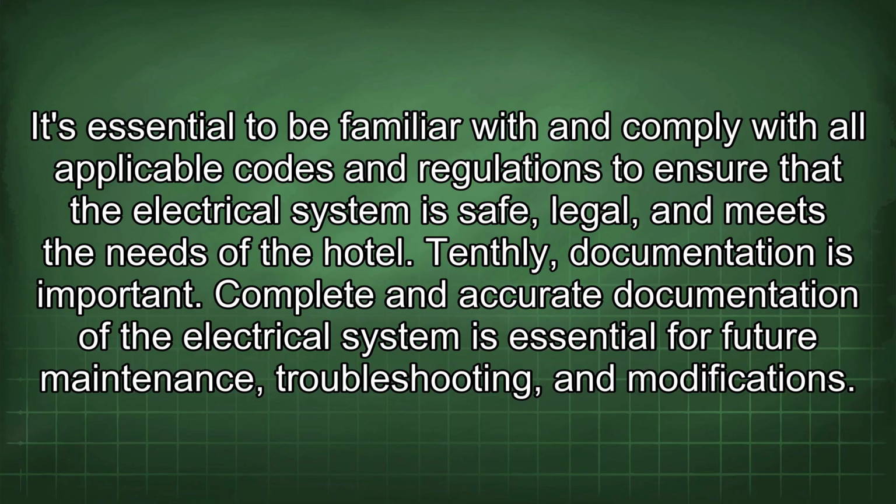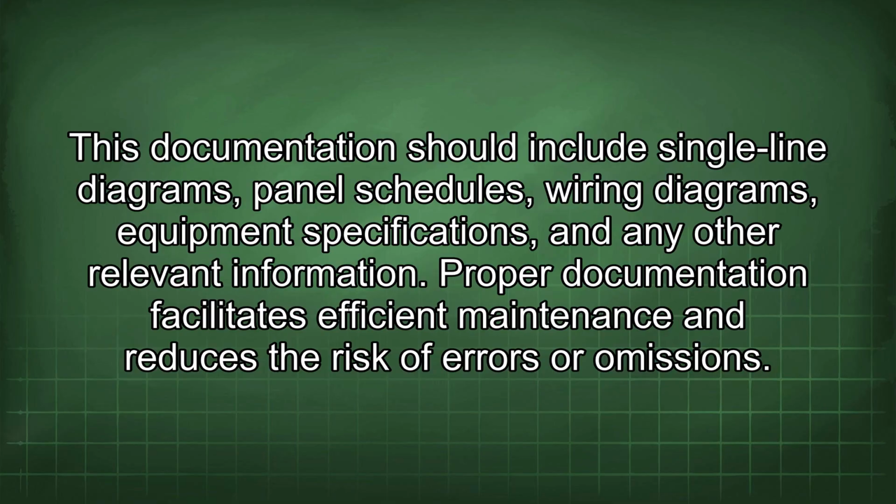Tenthly, documentation is important. Complete and accurate documentation of the electrical system is essential for future maintenance, troubleshooting, and modifications. This documentation should include single-line diagrams, panel schedules, wiring diagrams, equipment specifications, and any other relevant information.